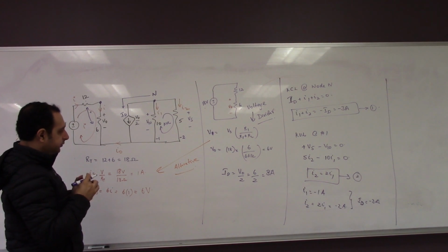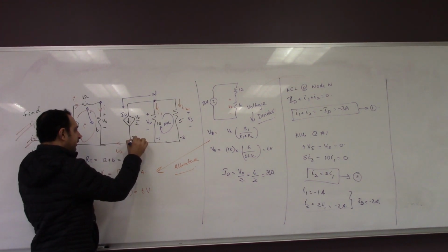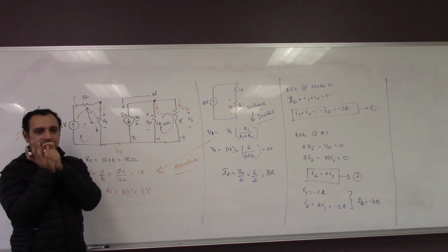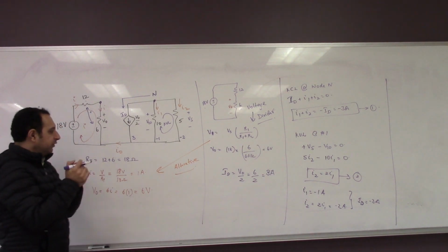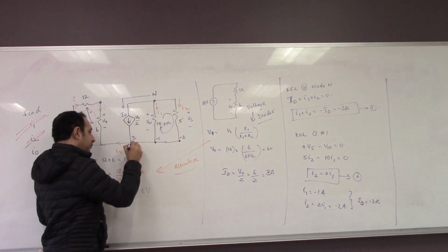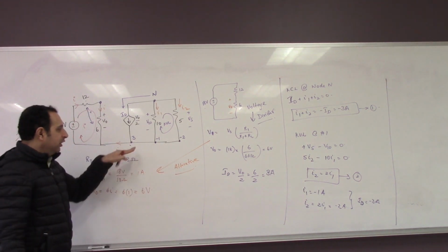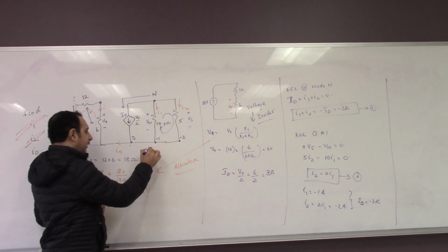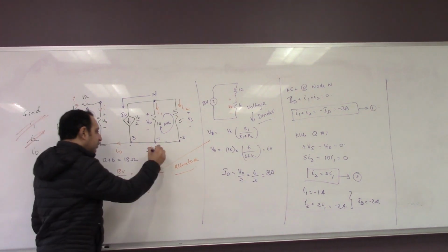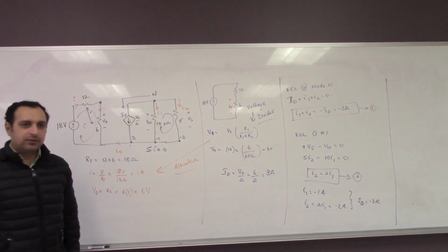Right. And then the 3. ID is 3, right? So ID is 3. Right? So it adds up to 0. Sum of all the currents at any node should be 0, right? So if I take over here, actually these 3 points are the same because nothing is connected between them. So the sigma I, wherever you might want to do that, is equal to 0. Okay? So what does it tell you about I0?